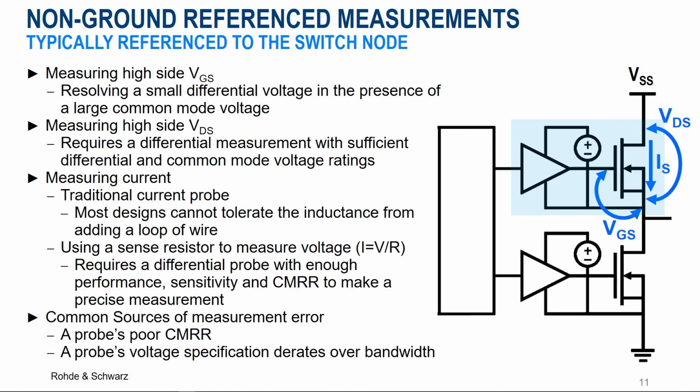While a differential probe is the best choice for getting the difference between 2 points, it is important to understand potential limitations due to a probe's peaked step response, probe noise, common mode rejection ratio, and effects caused by the probe's long input leads. These limitations are even more pronounced when testing on power devices with fast switching rates and even nominal common mode voltage.